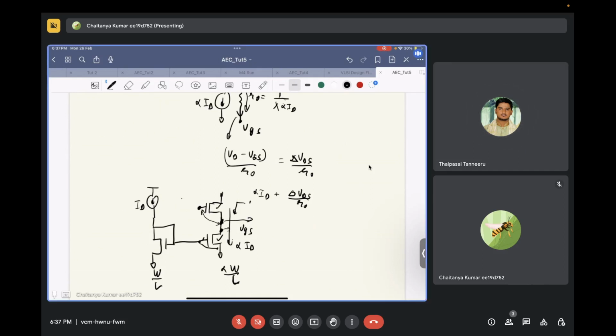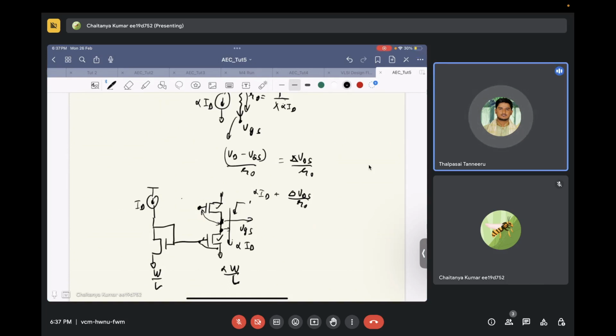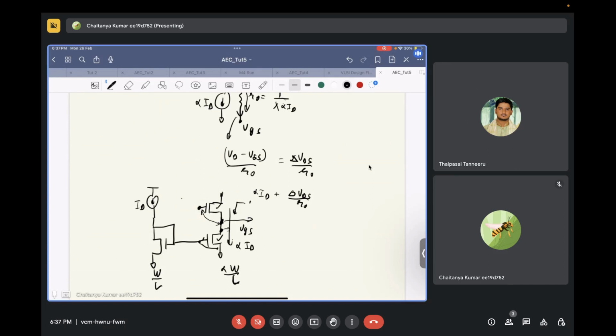Okay. So now what will you do? Now let's say this particular transistor has some VGS. If this is VGS, what VGS will be developed across this particular transistor as well? So what should be the gate voltage of this transistor? Sir, the bias voltage of the transistor will be VGS plus VTH. VGS plus VGS. Yes, one more VGS. So here you need to put two VGS.